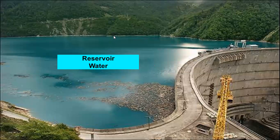Now this type of dam, we already discussed, which dam is it? It is an arch type of dam. It resists the force of water by the arch action. So this is the arch type of dam. It is having the vertical wall. So in this type of dam, you may not have the trapezoidal shape. You may convert it to a buttress dam to give extra support, but basically it is just an arch type of curve, as you can see in this image.